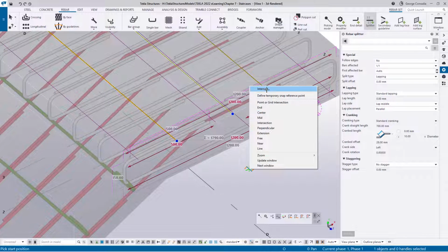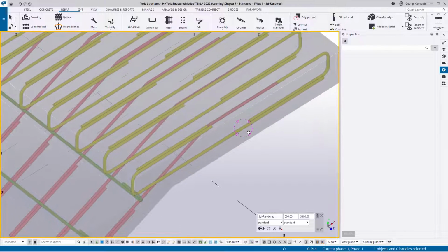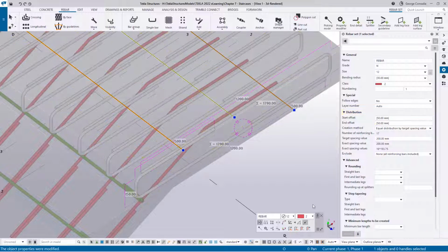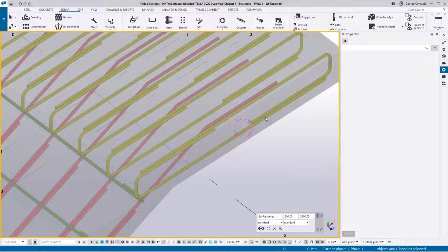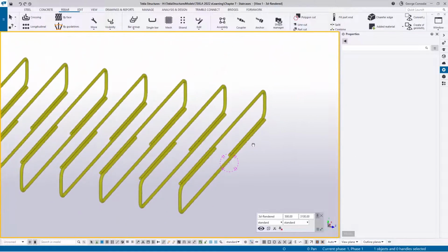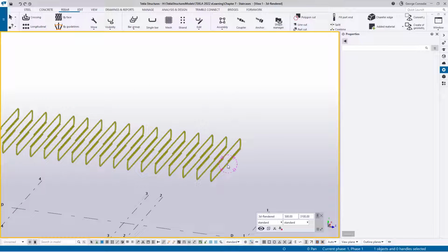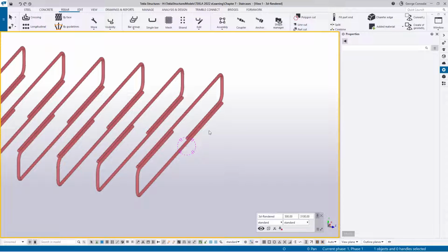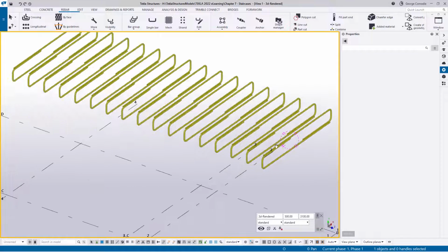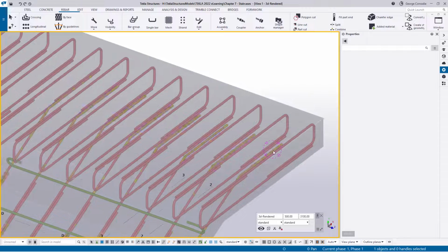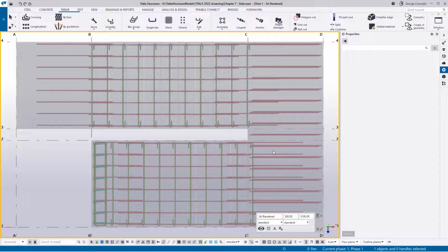And if you look at that now, what's happened is Tekla has now got, and maybe what we can do here is I'll just take away that spacing I put in. Okay, Tekla fixes it up by itself. If you look at this bar now, let's just isolate them. You can see what we have there is alternating bars. They are exactly the same bar. I mean, if you look at the inquiry, it's one line. It's exactly the same bar. It's got a 1200 leg and a 500 leg, but they sort of alternate upside down with each other. So it's a very effective way to reinforce. Let's just redraw all of that. So, okay, let's just look at the spacing quickly for a minute.